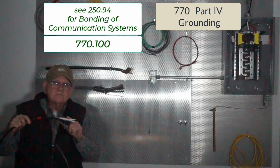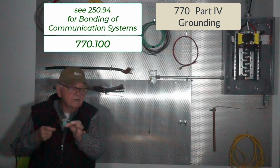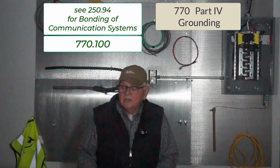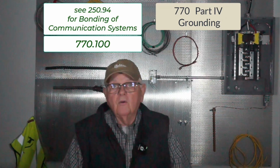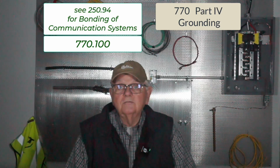Now, the minimum size of my equipment bonding jumper to run from my metal sheath over here to my intersystem bonding termination is going to be 14 AWG. So you can find all of those rules then in 770.100 and Part 5, Grounding Methods of Entrance Cable.